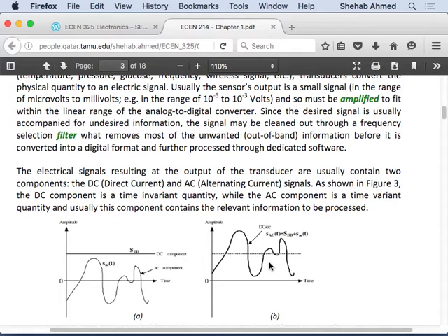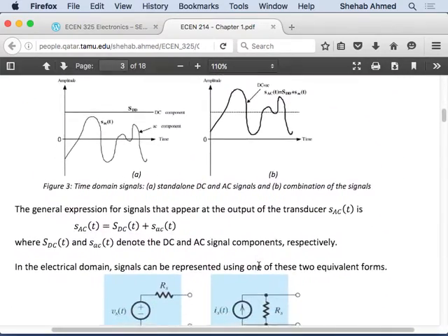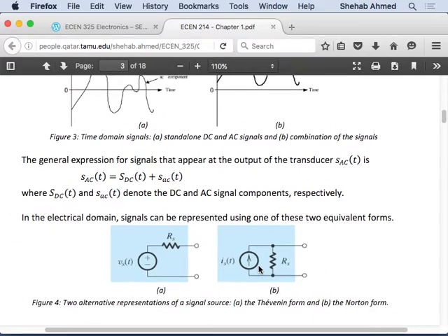So if I take this and chop it up using Fourier series or Fourier transform, I will find components at many different frequencies. So I need to make sure that I'm able to process something like this. I have to characterize my amplifier for various frequencies, right? And that's going to lead us to the frequency response material that is similar to 314.